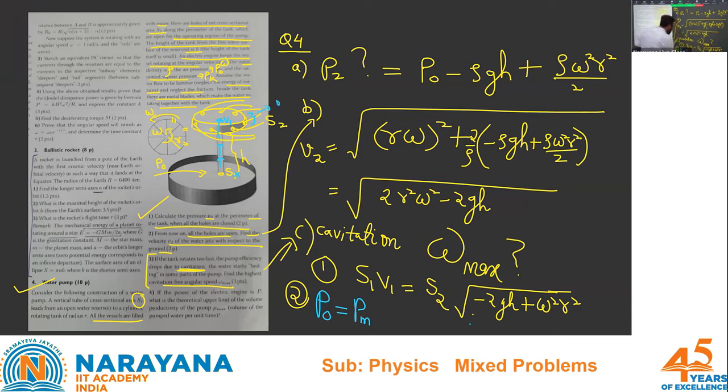So P comes in, plus I will have a rho GH term, plus I'll have a half rho V1 square term. Half rho V1 square term. This much is fine. Solve these two equations. Substitute your V1 here and try to find out PM.